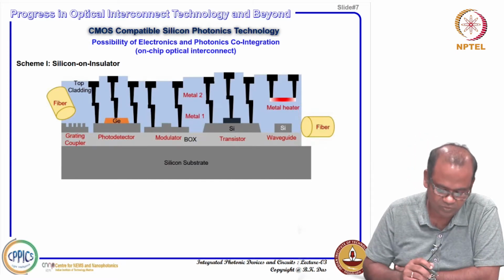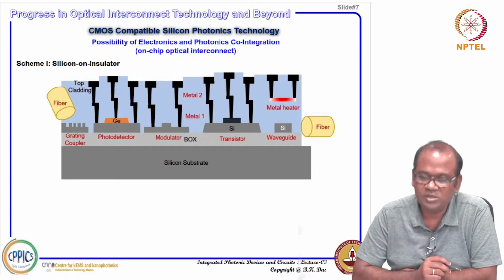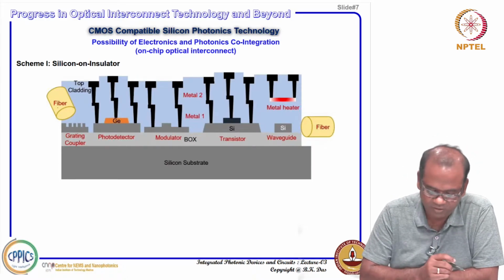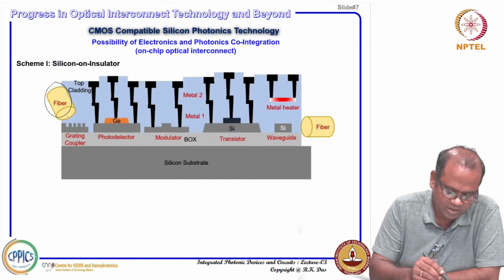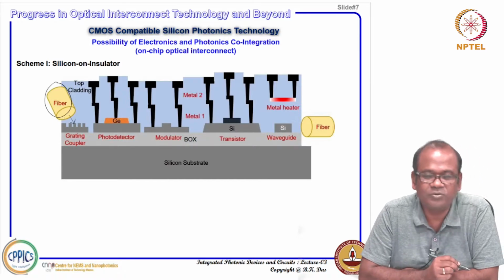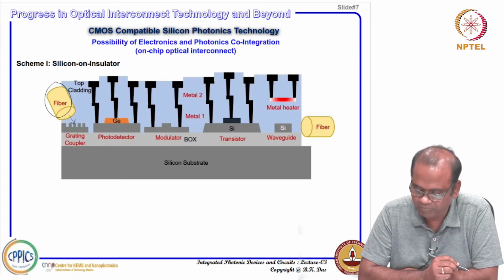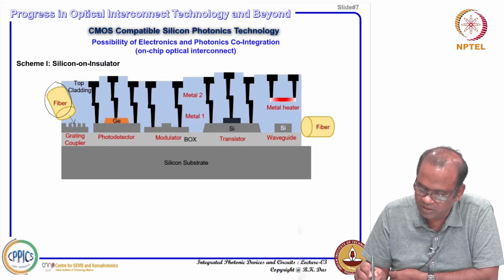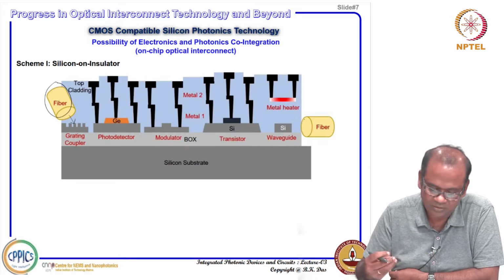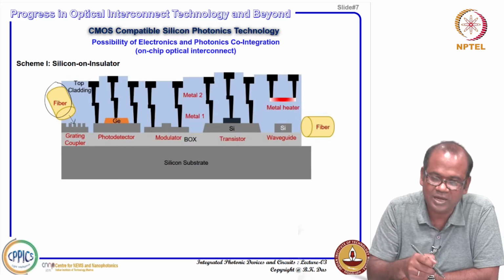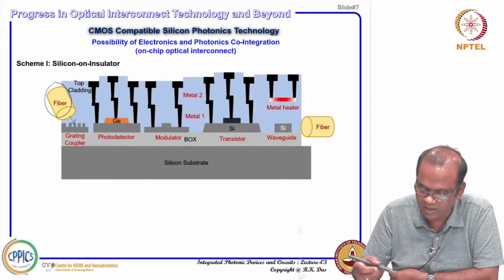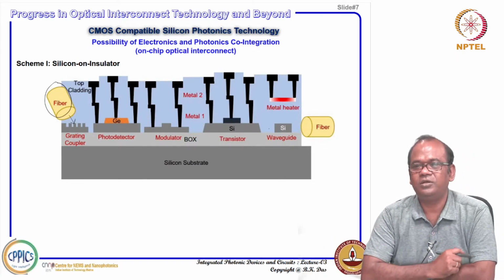For example, here it is shown, okay, silicon platform, a silicon laser cannot be fabricated on chip. You can use an optical fiber and get a grating coupler, and you can also use the fiber in line. You can shine light from the top, or you can shine light from the edge, you can couple light into the waveguide.